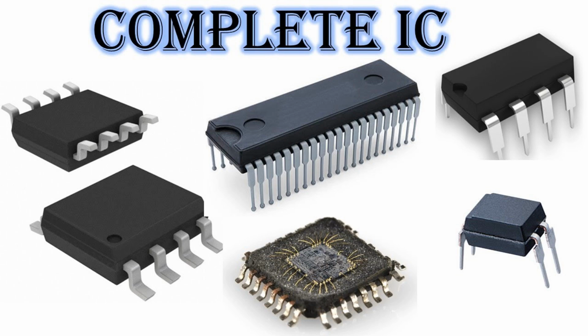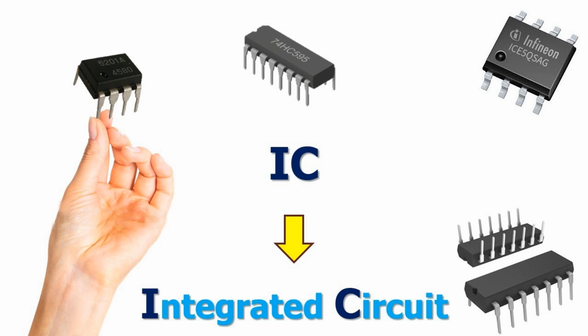Applications. Counter ICs are used in applications like frequency measurement, event counting, digital clocks, timers, and pulse generation. Synchronous versus asynchronous counters. Counter ICs can be either synchronous or asynchronous. Synchronous counters use a common clock signal for all flip-flops, ensuring that they change states simultaneously, while asynchronous counters can change states independently. Shift register ICs.